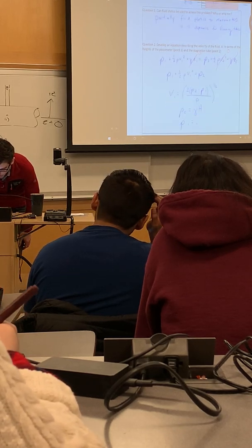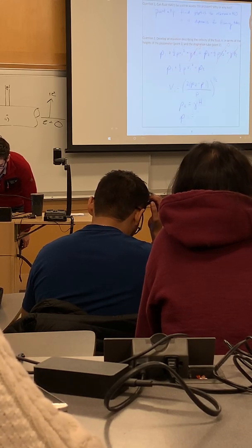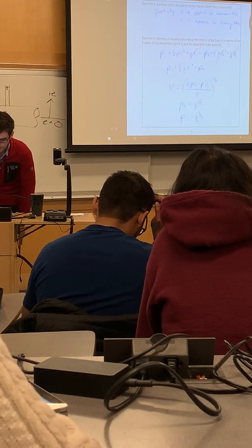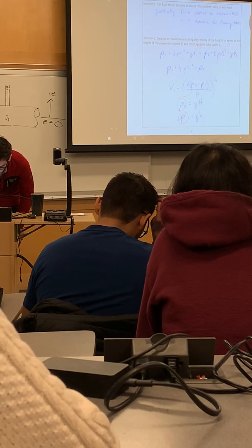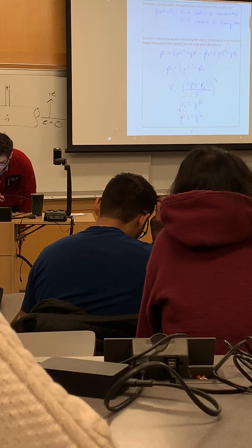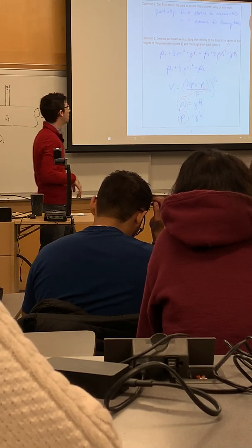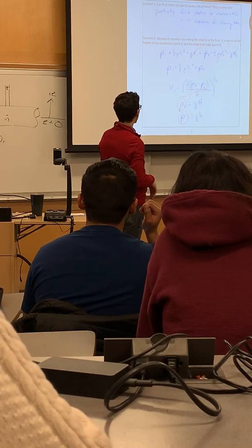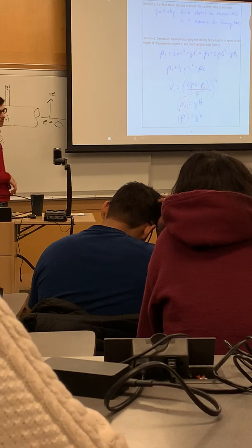At P1, we can do the same thing. We have a different height, little h, right? So plug those in, and we develop an expression for the velocity as a function of the changing heights of those vertical hydrostatic tubes. Okay.